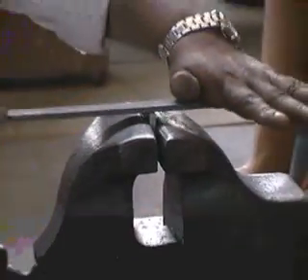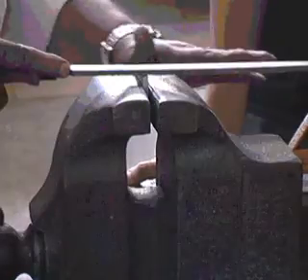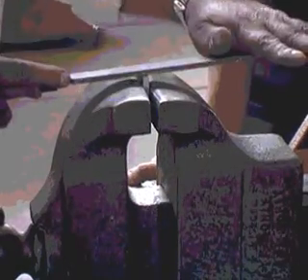The file should never be used in a tilted position. The file should be balanced and should be straight. If we move it in a tilted direction, the job will also get tilted. We check it using a tri-square and check our 90 degrees as shown in the video. Now we check using vernier calipers the length of the job.